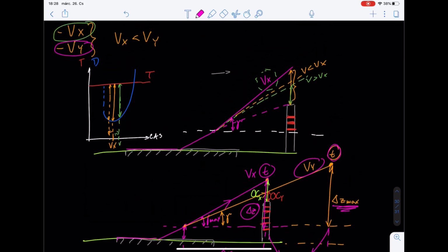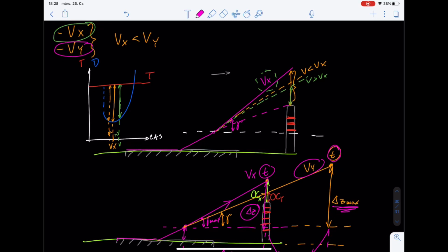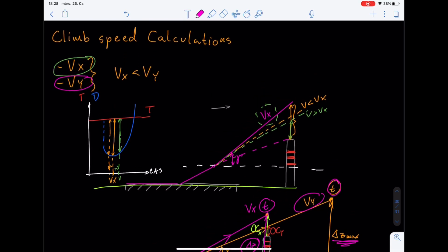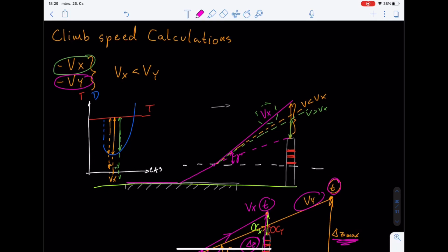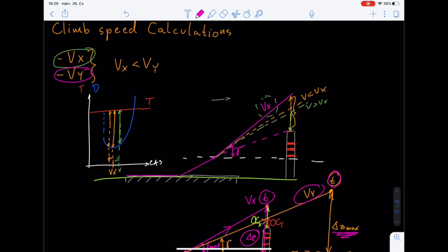So practically speaking, these are the two kinds of speeds which you want to maintain, and you will find these speeds for any aircraft you will be flying, and it's not just for the jet. The Piper has these speeds published in the pilot operating handbook as well, and you'll be required to know these speeds. It's very important that you understand what these speeds are for, because from my practical experience I see that a lot of students are afraid to climb at a slower speed, for example over a very congested area, where in reality that's what's safest, right?